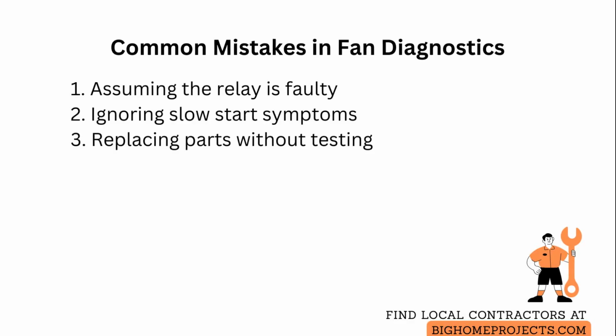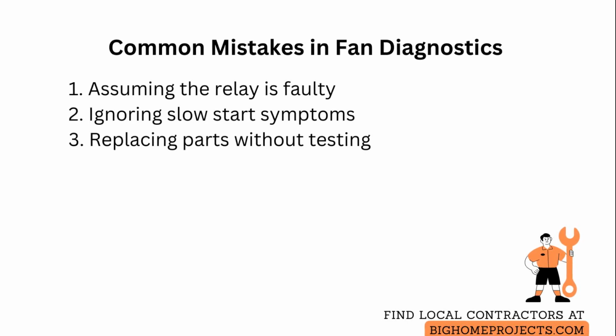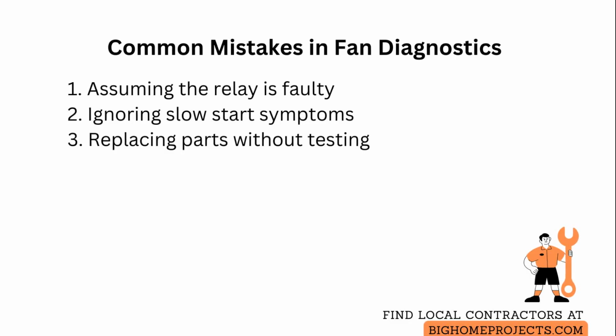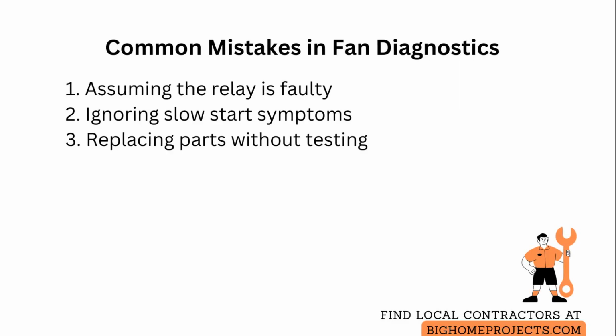A weak capacitor often measures low capacitance and high equivalent series resistance, so replace it rather than changing the switch. For motor winding concerns, take safety precautions, label and photograph wiring before disconnecting, and use a megohmmeter if insulation failure is suspected. When in doubt, swap in a known good capacitor and measure changes before ordering a new motor.